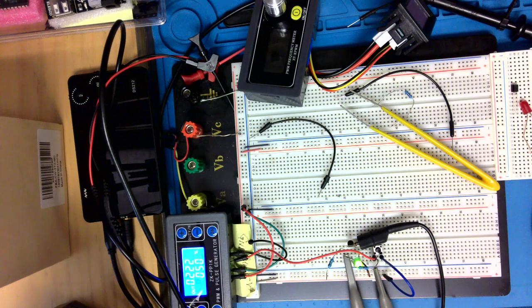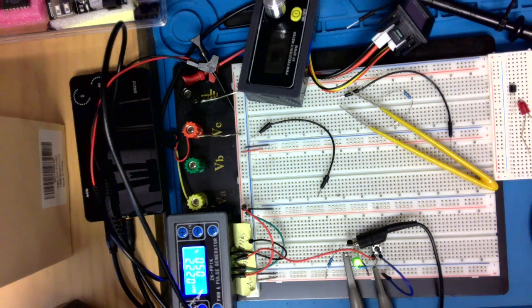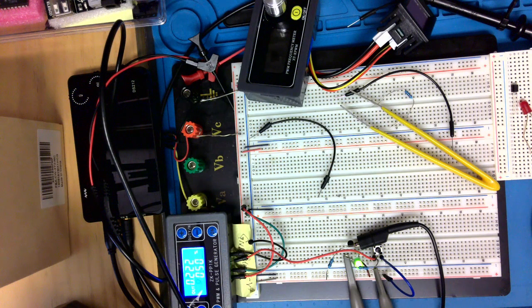In the old-fashioned TTL, the transistor goes into saturation mode. When the transistor is saturated, it creates a lot of, for an NPN transistor, holes in the base area. And when you turn it off, all the holes have to be removed, and they are removed by recombination. This recombination speed is very slow, and that's why TTL is generally very slow.